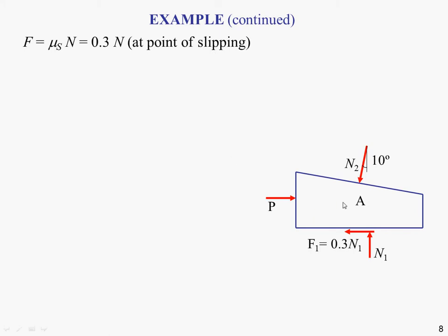So returning to our free body diagram of the wedge over here, we've also got the weight of the block down onto the wedge through the rollers, acting on this top surface of the wedge. There's no friction force parallel to the surface because we've got rollers, so we've just got our normal reaction force perpendicular to that surface.